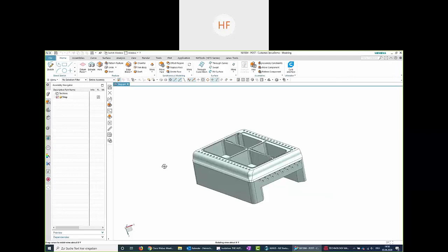For this, I also will use another manufacturing set. I'm just making a right click, insert. I want to insert a geometry as I, as a human being, have recognized a geometry in here. In my templates, I have the possibility to select a freeform. And then here it already tells me to select all faces for 3-axis copy milling. Okay, so let's do that.